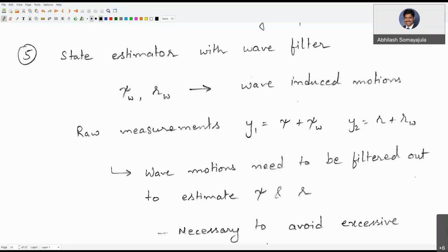And that will cause a lot of wear and tear on our actuators, which we don't want. It's only an oscillatory behavior which we are not really interested in. We want the overall heading to be more or less constant. So we have to filter out these high frequency components from the measurements, eliminate them, and only pass what is left as our feedback to our controls.